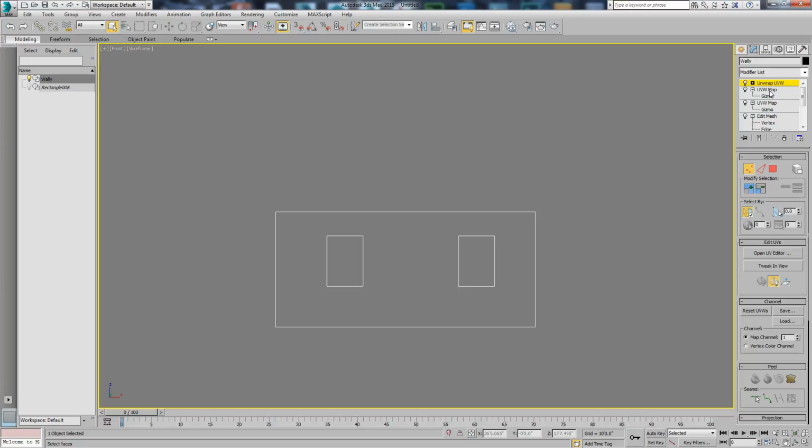Now, when you do this, this little window will pop up, and it says, do you want to move or abandon? Move means we want to copy from 1 to 2, and I don't want to do that. I'm just going to hit abandon, which means that I just want to use this coordinate that's in there. So now when I open this up, you'll see there it is. There's my mapping coordinate, which is the same as that square I had put on there. So I don't really need to do a UV Unwrap because I'm just doing a planar map in here.